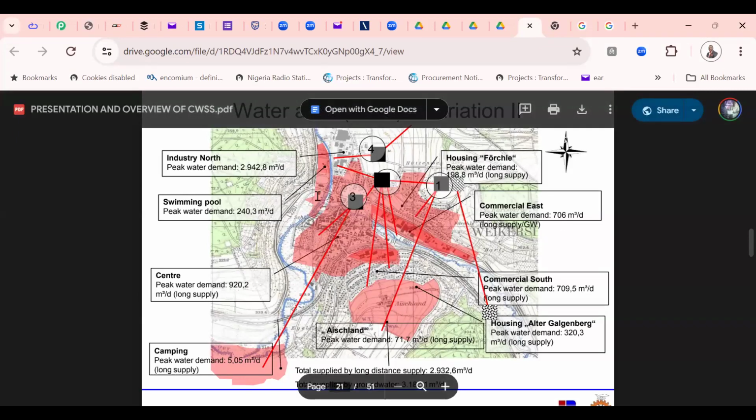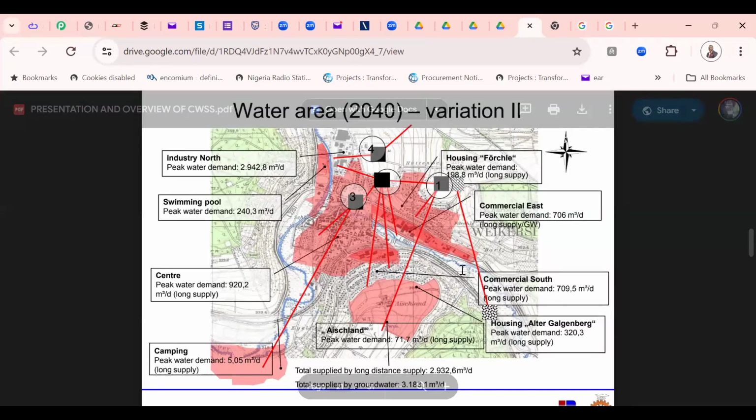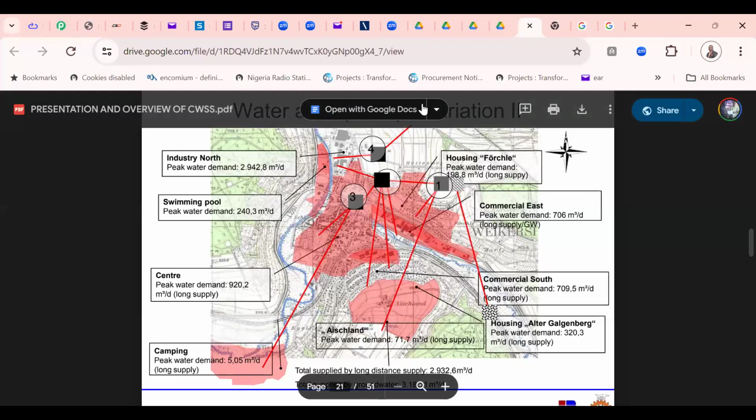So this is the assignment for this week. Design this. Why I'm saying this is that some people just design the mains. I've seen a design from the Federal Ministry of Water Resources for Ofoma, somewhere in Umuahia, and I discovered that they just designed the main. And I don't blame them, because once you design the main, people will just come and tap in and the thing will work. But when the main is wrong, everything is wrong.